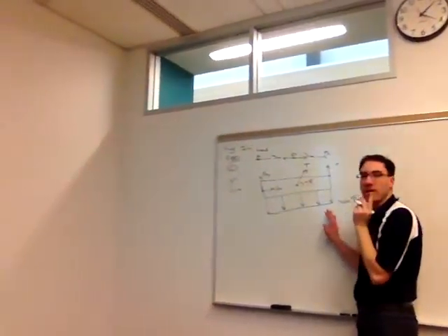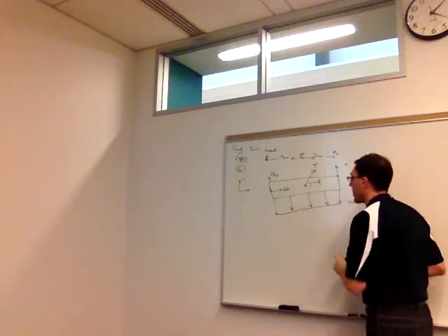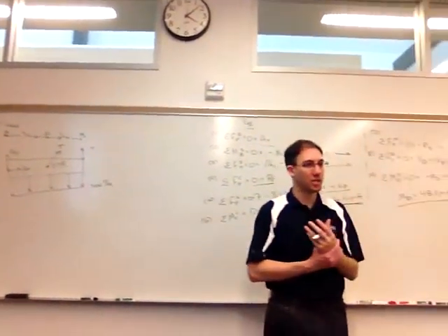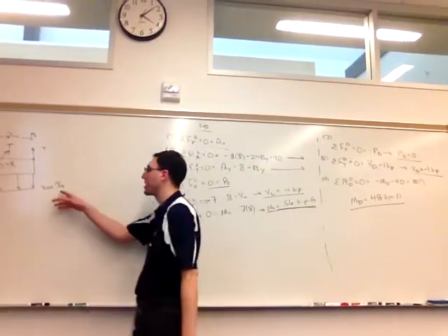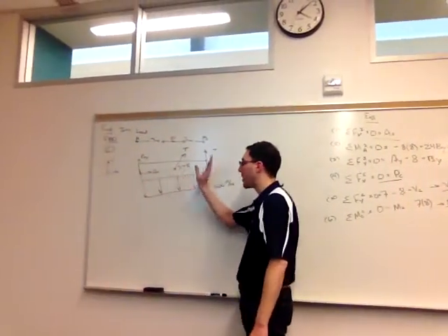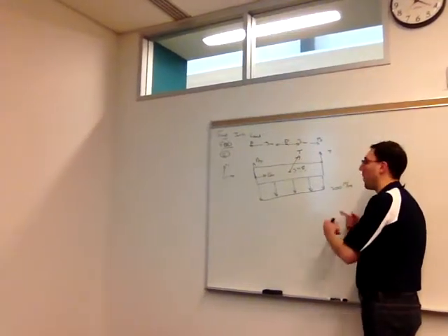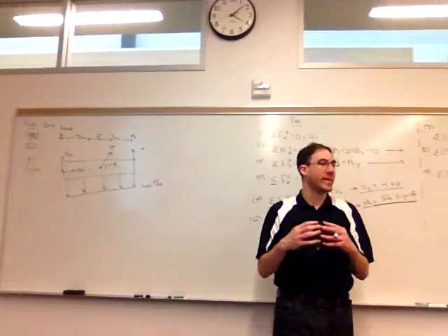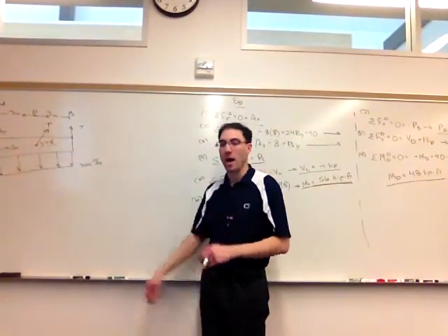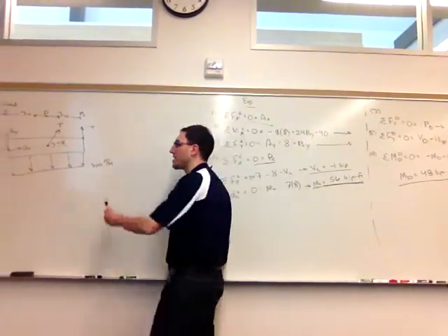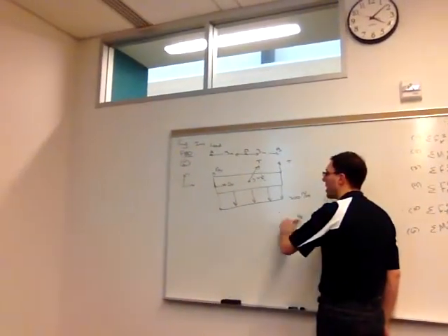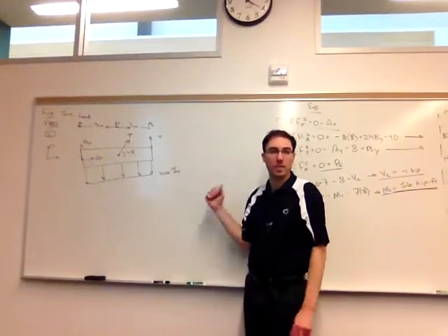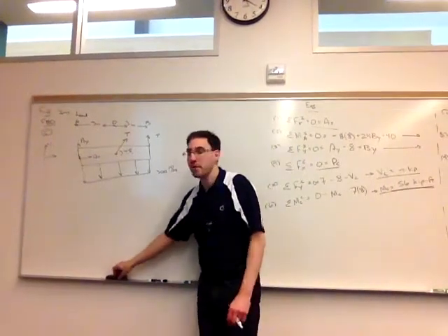For the picture, I'm going to leave the distributed load as a distributed load. Like we talked about when we first talked about distributed loads, externally, we can simplify this down to just a point load, and we can run all of our analysis that way. However, if we do that, that's good externally, but internally, we can't make that simplification right off the bat. We need to keep it as a distributed load. So I recommend keeping it this way, or else we could forget that it was originally a distributed load, and that affects the pictures we're going to draw downstream.